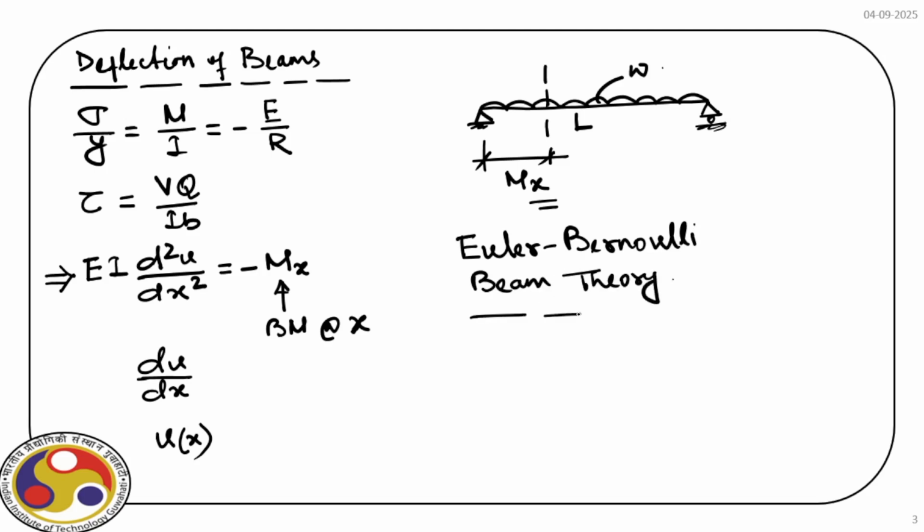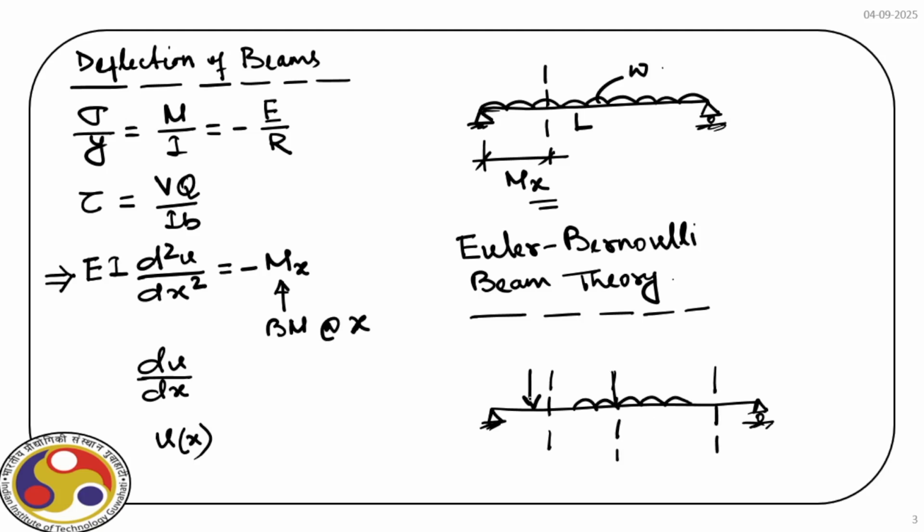Right. Now, not always we have beams which are under UDL over the entire span. For example, if you have, say, a beam, same simply supported beam, and we have a point load, then a patch load, then for this, the question arises where we should take the section. Is it here or there or here? And we can have different combinations of load, just like you can see here we have a point load and patch load.